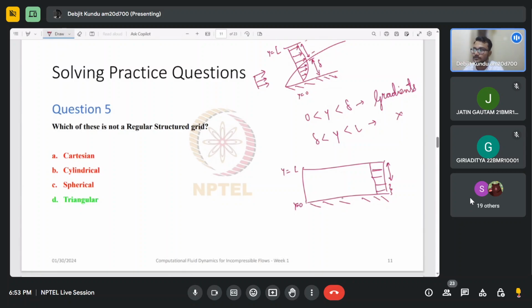So what we do is we refine the mesh in our regions of interest where there are more gradients involved. So this comes from physical insight. Beforehand, it's difficult to say so. Okay, there is a strategy when we can't say beforehand as well. I'll point you to that.